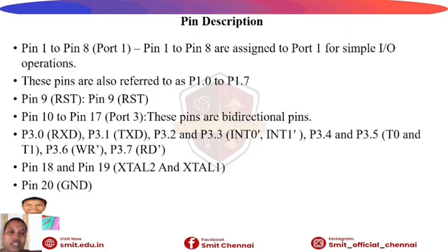Pin 9 is RST, which means the reset key, and pin 10 to pin 17 is port 3. These are bidirectional pins. Pin 10 to 17 is port 3: P3.0 is RXD, and RXD means receive data, and P3.1 is TXD, transmit data. Transmit data means transferring the data. P3.2 and P3.3 are the interrupt pins.